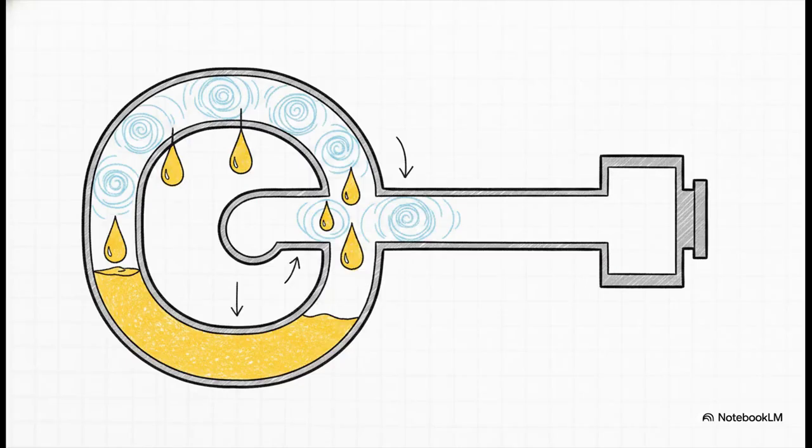But we have to remember, even if your chemical miscibility is 100% perfect, you can still suffer from something called oil logging. Say your cooling load drops, maybe it's just mild weather and you have a variable speed compressor running, your refrigerant mass flow just plummets. If that refrigerant vapor velocity drops below the critical threshold, which is about 700 feet per minute, well, gravity wins. The oil falls right out of the vapor and just pools in the coils, quietly robbing your compressor of its lifeblood until it completely seizes up.